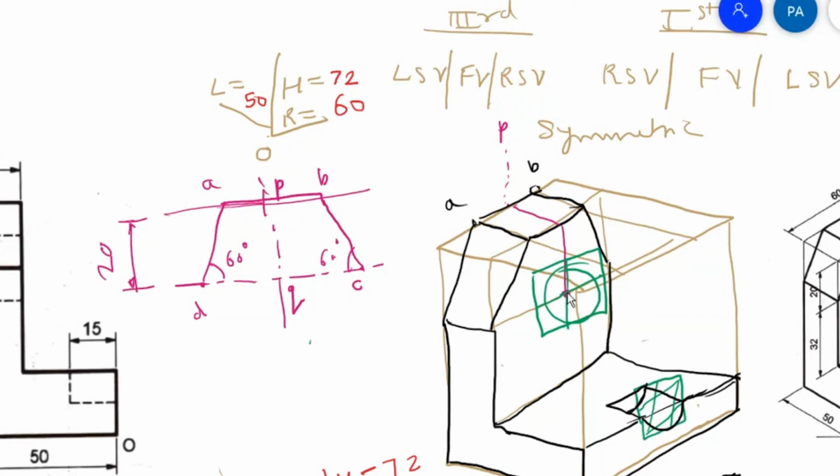Okay, and how to obtain this center? You know how to obtain this center. This center point is on the DC line, and on this vertical, 30 mm from this side and 30 mm from this side. And that has to be drawn on which face? Not on this face AB, not on the AB face. It has to be drawn on this face.